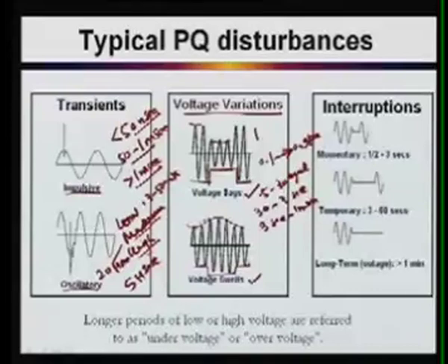So if your voltage dip is up to 1 minute, then it is called voltage sag. There is always the possibility that your power system can operate, especially in our country, with a continuous voltage dip, for a longer duration, even for hours, especially due to heavy loading. That is not a power quality problem, that is a different type of problem.